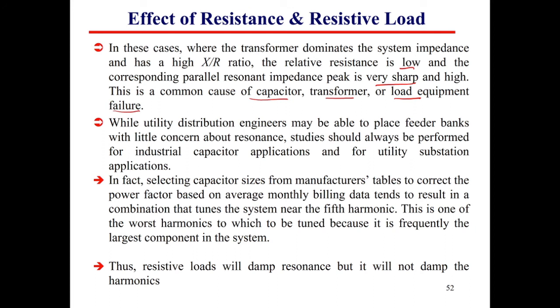While utility distribution engineers may be able to place feeder banks with little concern about the resonance, okay, so if they place the capacitor away from the transformer, at that time you should have no major issue with regard to resonance.